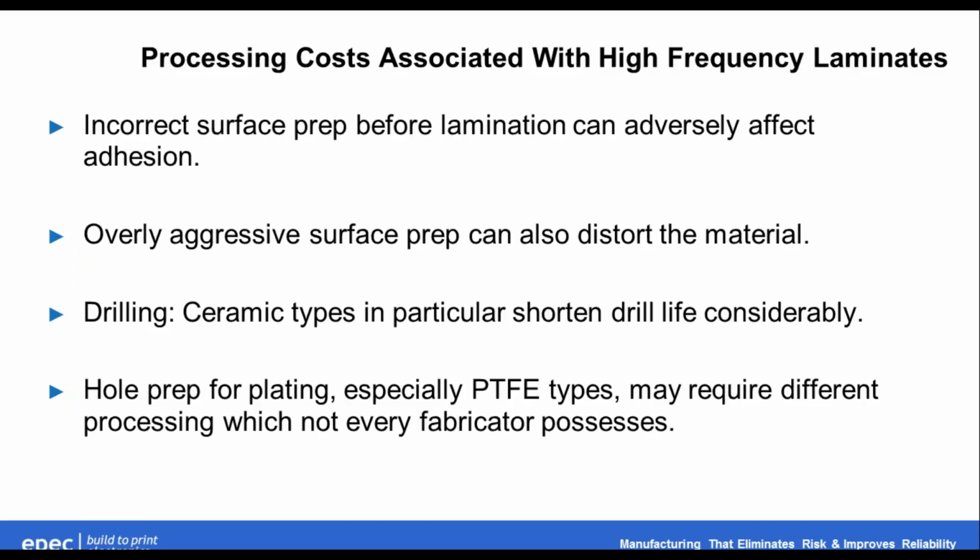All boards, after they're drilled, go through a cleaning process where the inside of the hole is cleaned out to remove any kind of residue that might have been dragged back through the hole when the drill was exiting the hole. And with these materials, you sometimes need to use different chemistries and different processes to get that out, and not everybody has them. So it's important that your fabricator understand the differences in processing before they commit to building some of this stuff, because anybody who's ever seen it done by trial and error, and I have, it's not pretty.